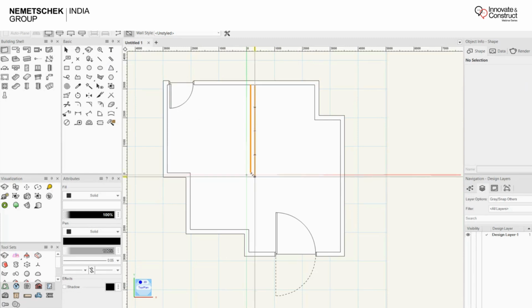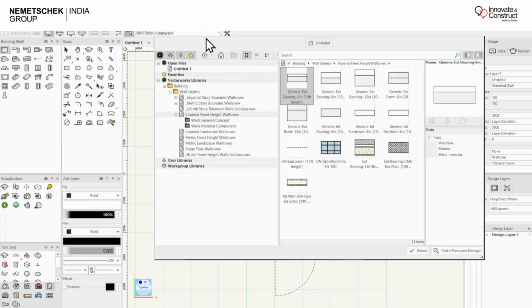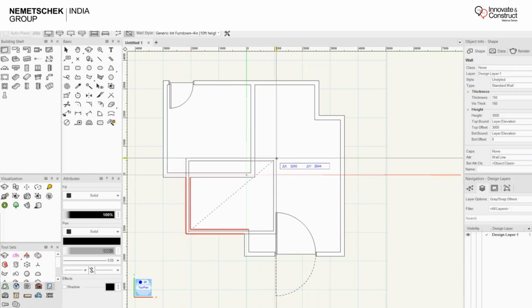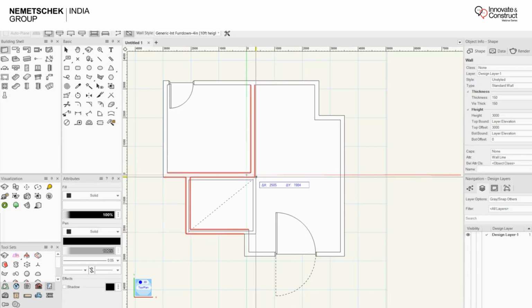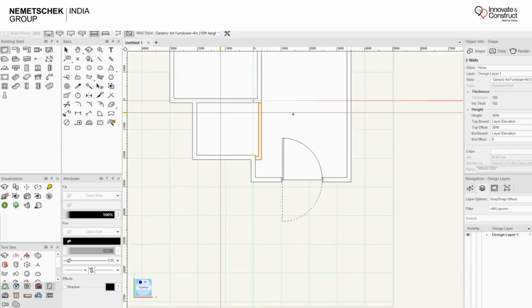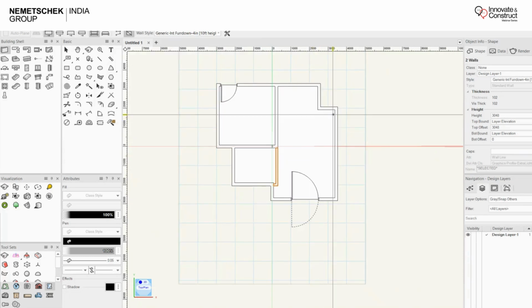But just to show you quickly, I am going to add this into the interior space. Obviously, I can define my interior walls as well, as required. While drawing those, it reads my interior space and will trim back. I don't need to draw those things. It will automatically trim back in whatever fashion. Further, I can update it, customize it, and build it however I want.